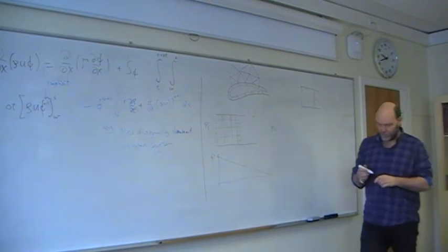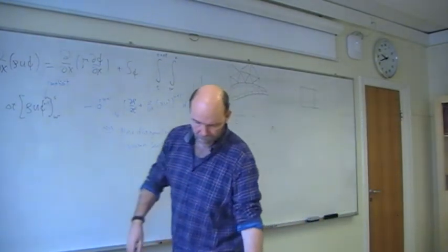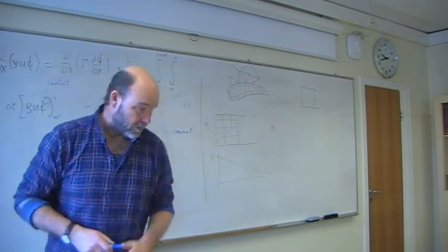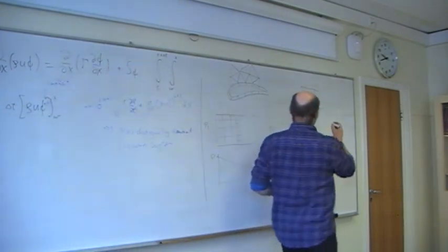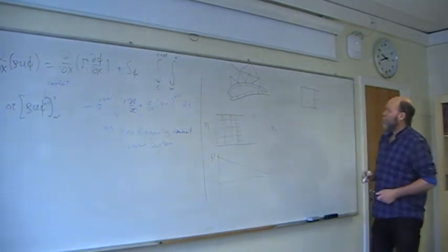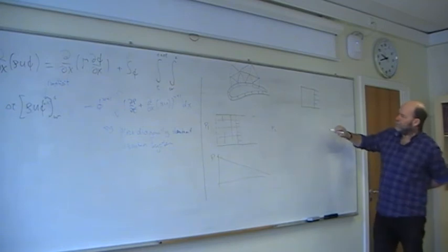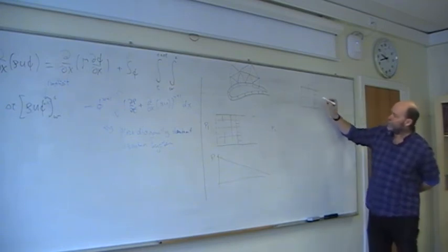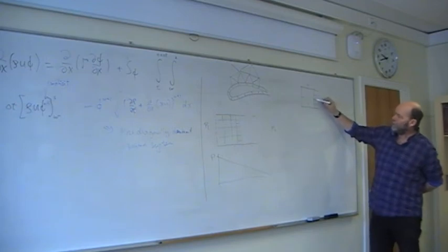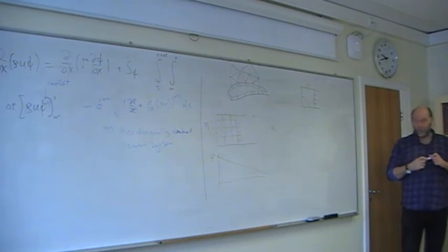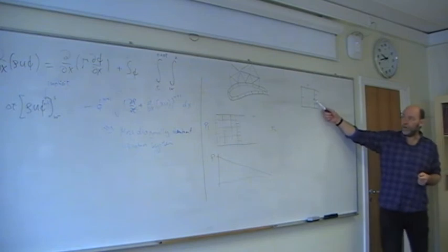So for the cells to the right there, they will now require input, say a velocity here and a velocity here. But from the big cell, well, maybe we have the staggered system, so we only have velocities on each face. So you only have one velocity here, which has now to be split into 2. Okay, then you need some interpolation tricks to do this correctly.